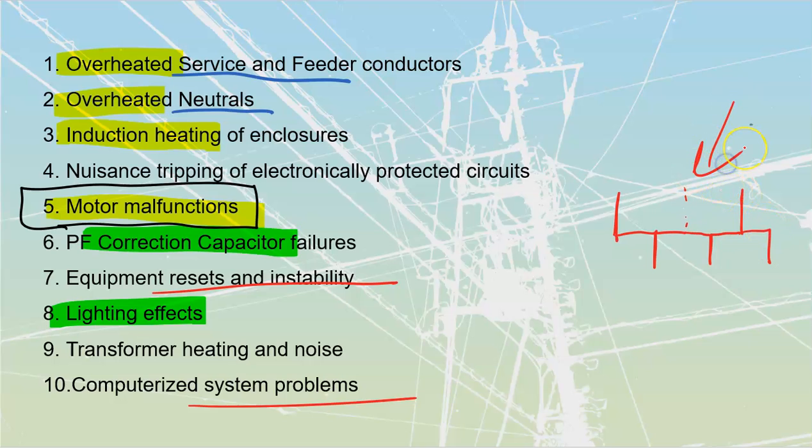What happens is if we miss a spike of current inside of these, we're going to get flicker off of our LED lights, and poor quality, low quality LED lights are going to be more susceptible to this than high quality. But your customers like to buy the cheap lights that they can get on sale, with a massive amount over at the Home Depot or things like that. So you will see these things start to manifest on the LED lights themselves.